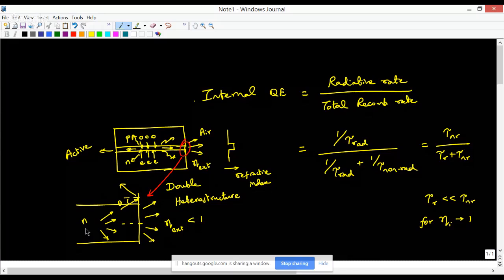So if you want to frustrate this total internal reflection, what you typically do is corrugate, or create some surface roughness at that interface, and with that surface roughness you can frustrate the total internal reflection, and thereby extract more photons from the structure, and have your external quantum efficiency increase because of that. So hopefully that answers the question.